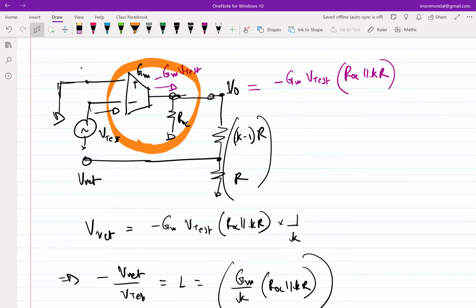It is often called the error amplifier. Because what is the essence of what you are trying to do in a negative feedback loop? You are sensing the error and taking a corrective action. And in the process of taking the corrective action, you are also amplifying the error, right? So you are essentially finding out what this error voltage is.